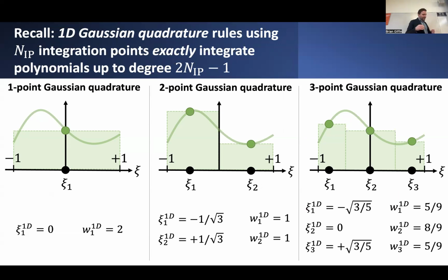So given that our finite element shape functions that we've constructed in 2 and 3 dimensions are also nominally representable as finite degree polynomials, as we've constructed them to be these interpolating polynomials, at least defined with respect to the element's parametric space, we should like to use a similar set of these integration formulas, but somehow we want to generalize it into the case of 2 dimensions and 3 dimensions. So how do we do this? Well, suppose we picked one of these different integration formulas. I don't know, let's just suppose we picked this 2-point integration rule in 1 dimension. Now, how do you suppose we could go about generalizing our integration formula into a 2-dimensional setting?